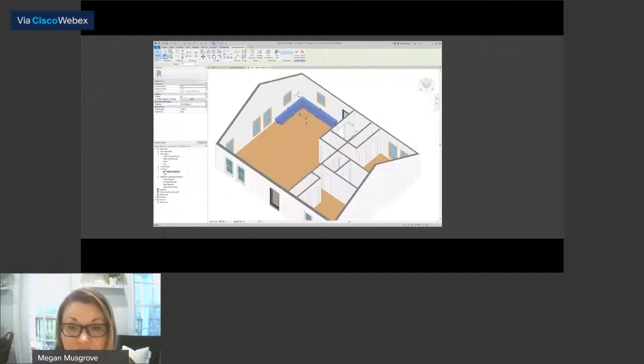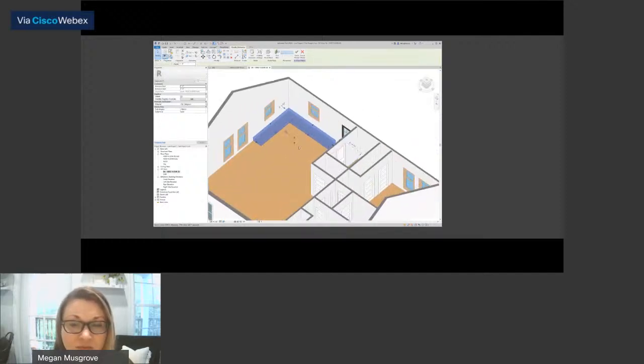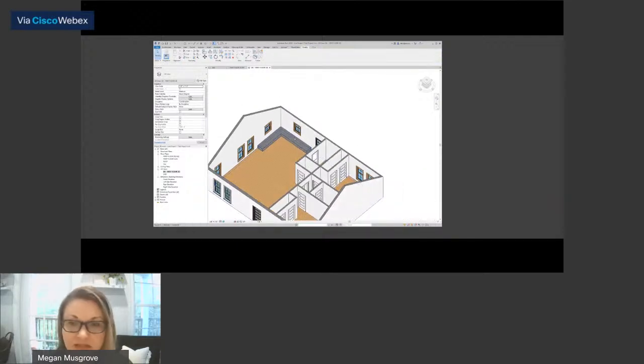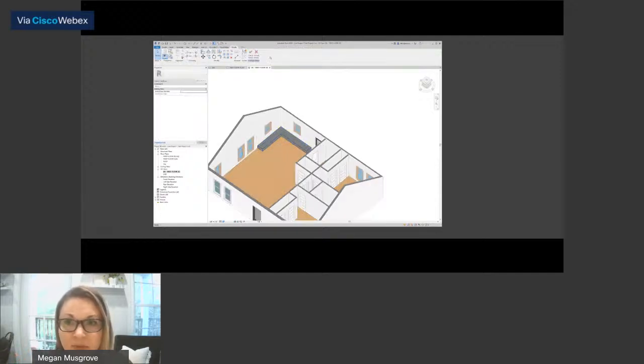Now, if we look up in here, it's showing we're still in the tool, but it finished. So we finished making that extrusion, but we're not finished with the family. If we finish the model, then we have finished that, and it's just got this ugly gray thing sitting here. Now we're going to click on it again. We can click edit in place, and we're going to click on that extrusion. So we made a custom in-place family that was a model, and it can be made up of different extrusions and other kinds of things and voids. Right now we only have one in there, so that's all there is for us to click on.